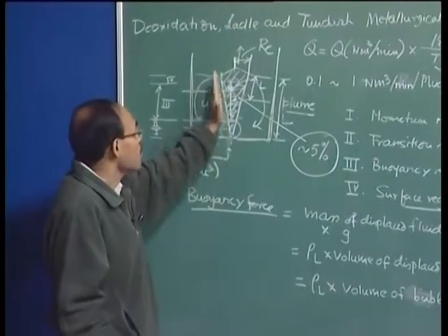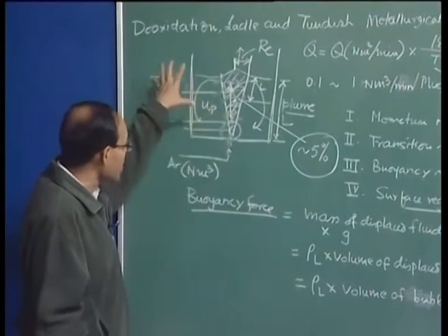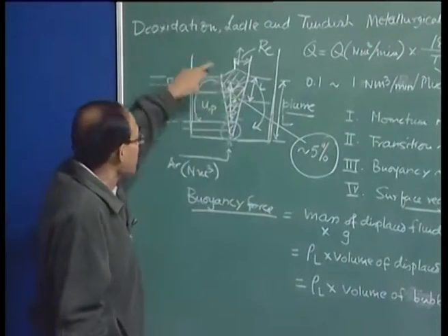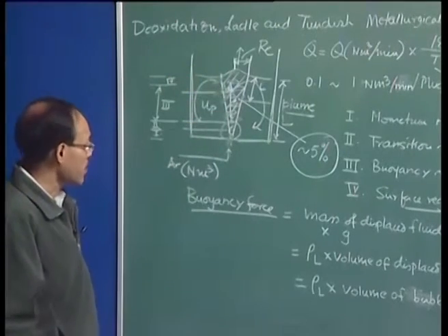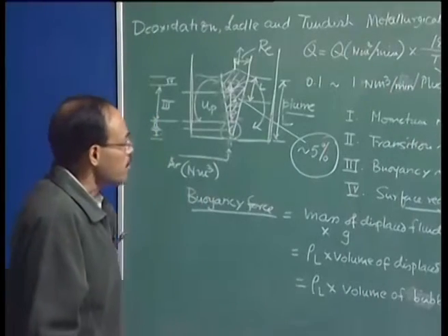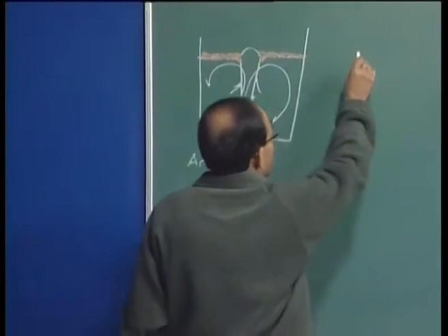So all along this, because of the buoyancy itself, energy is going to be continuously transferred. The bubbles are going to give away their energy to the fluid. While they leave the system, the fluid will keep on recirculating, thereby generating a strong convection current in the system itself. So I have introduced a term which is the plume velocity.